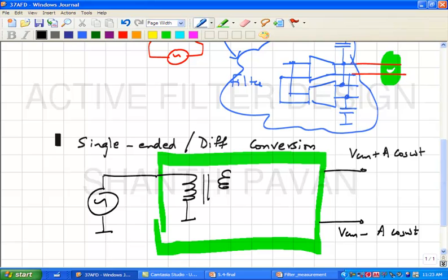There is something called a center tap transformer. There is nothing great about it. You can take two transformers, if you do not know what a center tap transformer is, and then equivalently reverse the dot connection, right. So basically a center tap transformer is something where you have access to the central tap. If all the turns are the same, then all that the induction law is saying is that the voltage between these two points is twice the voltage across the primary turns, correct.